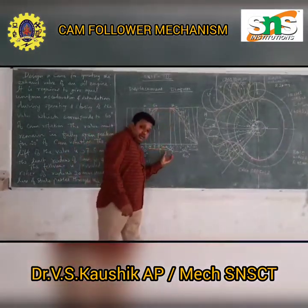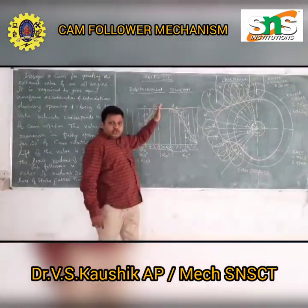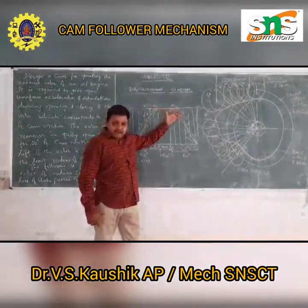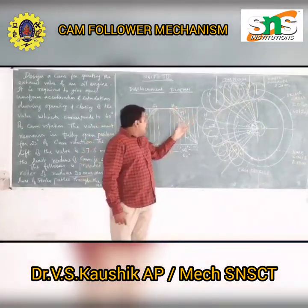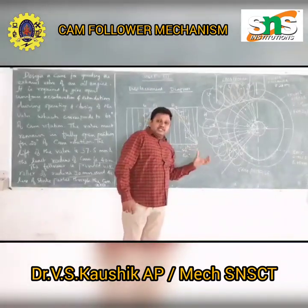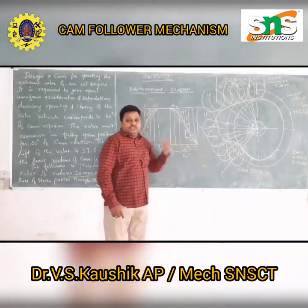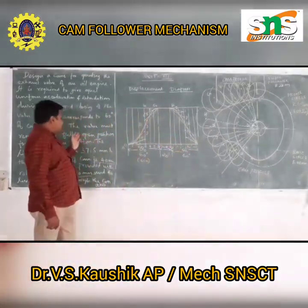That is what dwell means: the cam will open during the stroke and it will be left open, and after 20 degrees only the cam retards or closes or comes back to its original position. That is what is given here.